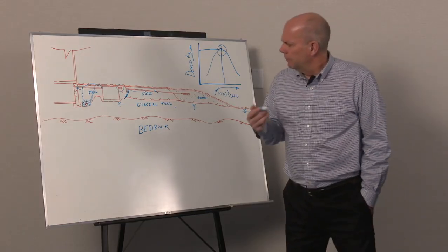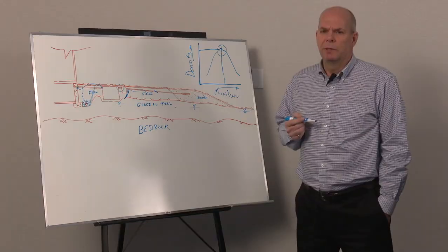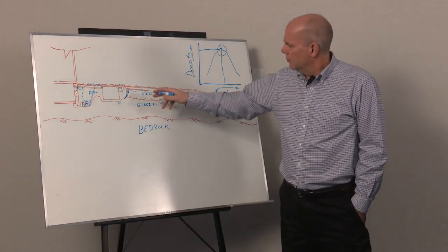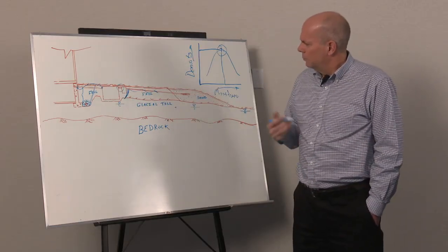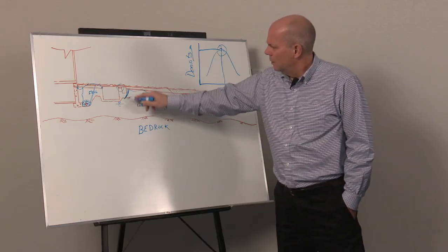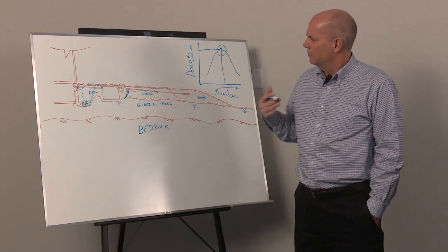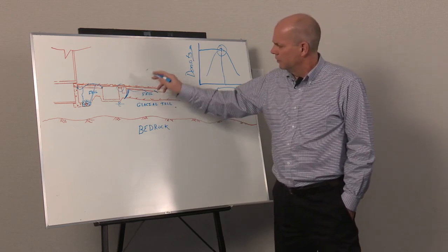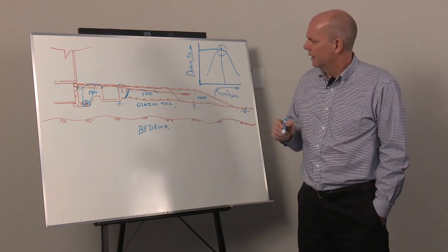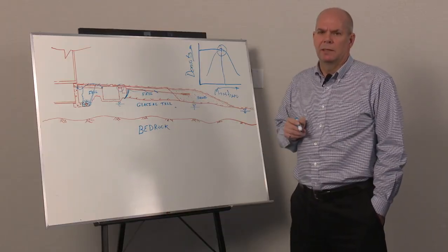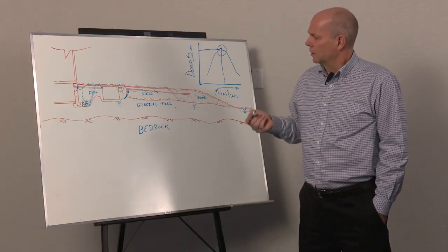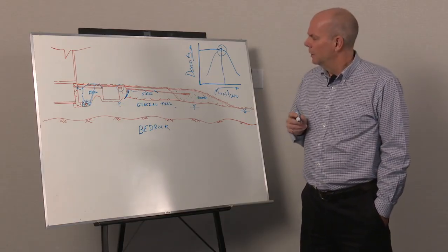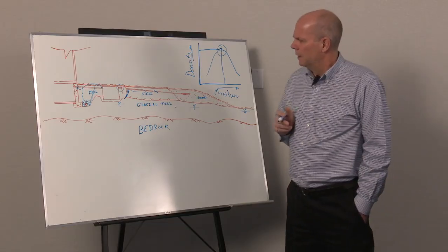So the lift thickness has to be compatible with the equipment. Make sure you're placing the fill properly against all the backfill around these things, because the pipe has to cross over any of the fill you place. Even if there's no existing fill and you're just digging a hole in the glacial till for the tank, you still have to reinstate that excavation with excavated material, and the effluent pipes are going to be crossing through that, so you have to watch out for that.